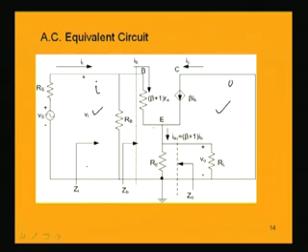base-emitter circuit, that is, the transistor is being replaced by its model. So, the emitter-base junction as usual has the resistance (beta plus 1) Re. The current flowing through this (beta plus 1) Re is Ib, and from the emitter point the current flowing is the emitter current, (beta plus 1) Ib, and this is the collector current, which is beta times Ib. Beta times Ib and Ib join here to give rise to the total current, which is the emitter current.